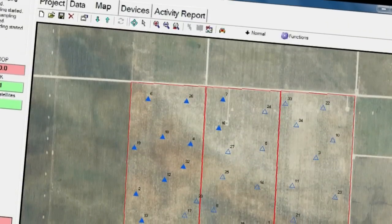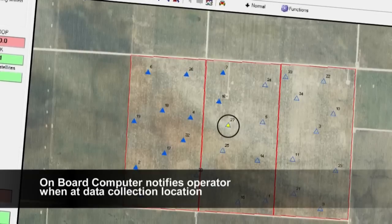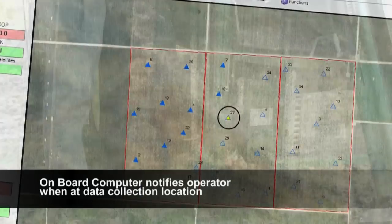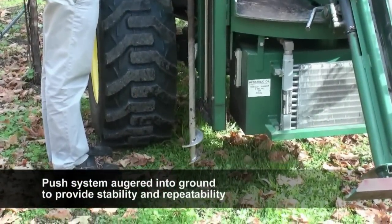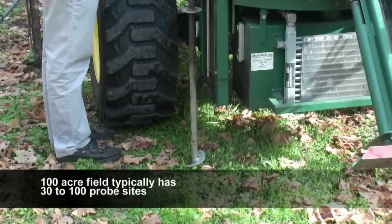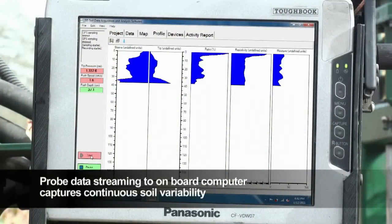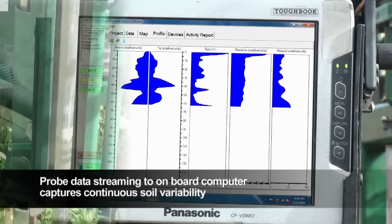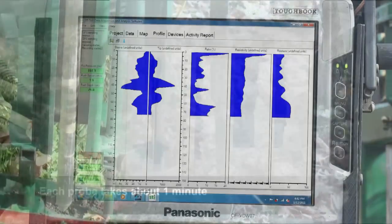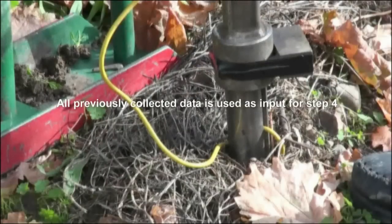Continuing on in Step 3, the diver software guides the operator to a point. Anchoring the system into the ground at this step will ensure all measurements are repeatable. The geophysical probe is pushed into the ground to collect continuous data streams for tip force, sleeve friction, moisture, and electrical resistance. Monitoring data signatures using the onboard computer while the data is being collected helps STI ensure data quality. The entire process takes approximately 5 minutes to collect data at each location.